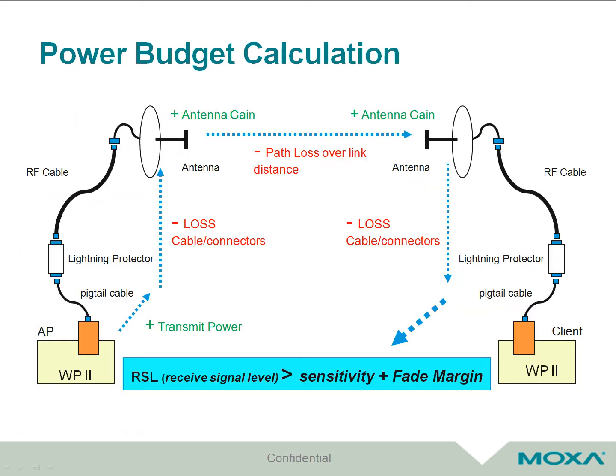To make sure that our wireless communication will succeed, we have to calculate signal power on receiver's side, taking into account the influence of our environment and system components. If the calculated signal power is higher than receiver sensitivity, we can then say that our wireless system will probably work. This slide is showing you typical components that you have to consider. The transmitter itself and antennas make positive contribution into signal power. Cables, connectors, and air, on the other hand, reduce signal level.